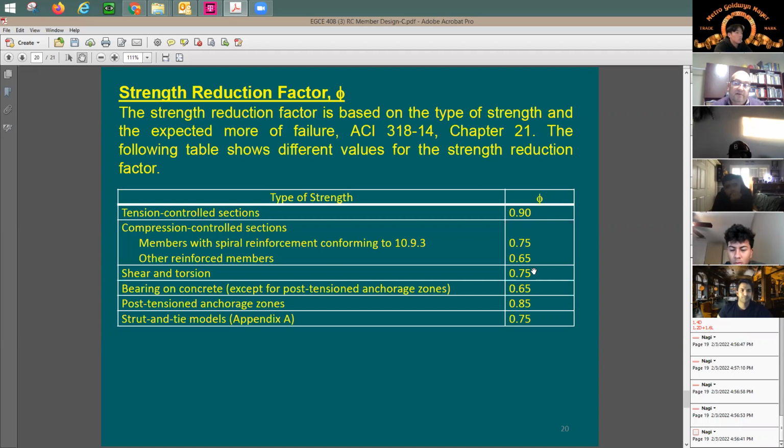When you go here to concrete, let's say that you are pouring concrete, and then you take a cylinder and then you test it. You'd assume that this concrete cylinder represents all the concrete. But reality is, when you are taking the sample, they give you the best concrete in the truck. And the rest of the concrete in the truck, they're going to be adding more water to it. So the cylinder that you have taken is not really representing the concrete that you cast in this slab or this footing. So you got to be careful, right? In your design, you need to reduce the strength a little bit to account for all of these problems.